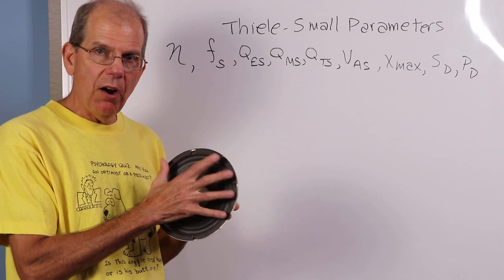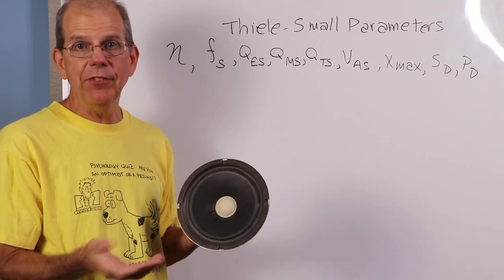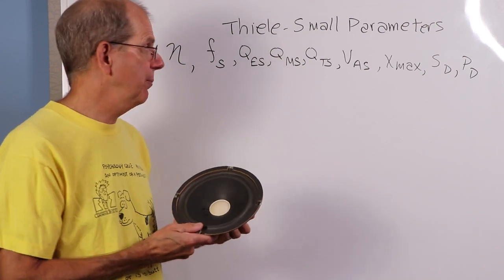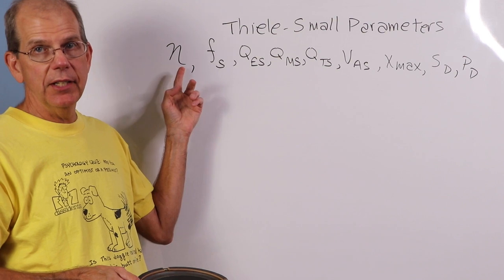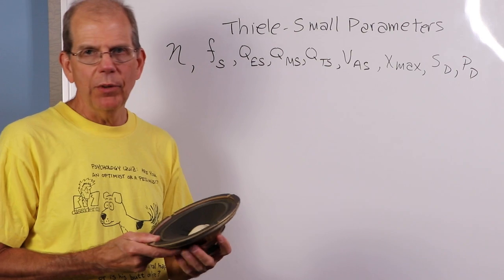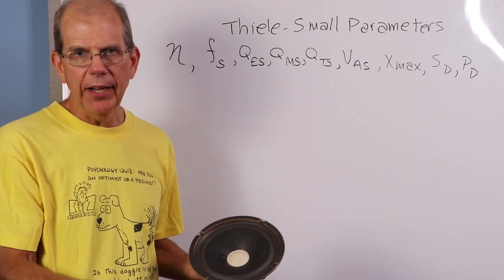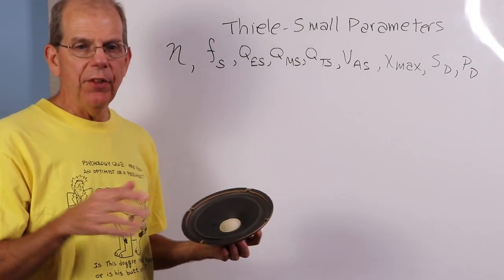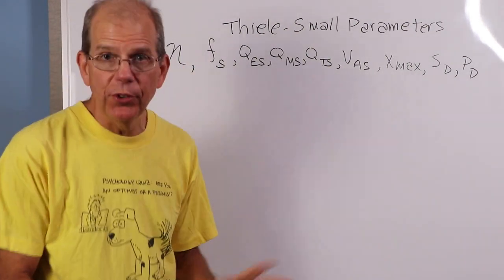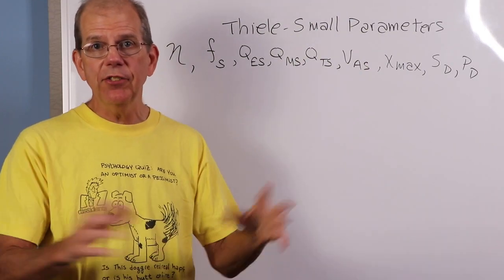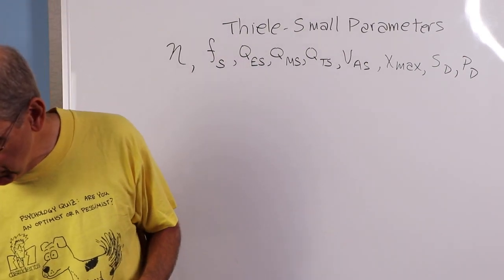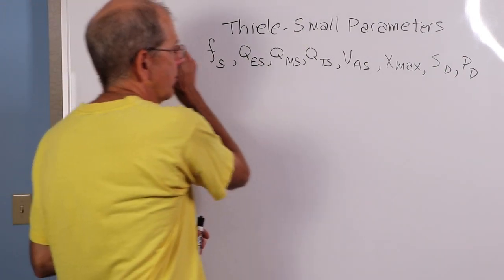If you go to a bigger cone, the cone itself is going to be more massive. It's going to have more mass. That makes it harder to move. That affects its transient response. It may adversely affect the efficiency. So you try to tweak one thing, and that has a side effect. What's the overall issue that we wind up with? All of these things kind of come together. That's our transducer. It doesn't matter if it's a 4-inch or a 15-inch, that's the physics of it. Now, there's one equation you need to remember when we talk about direct radiating loudspeakers.